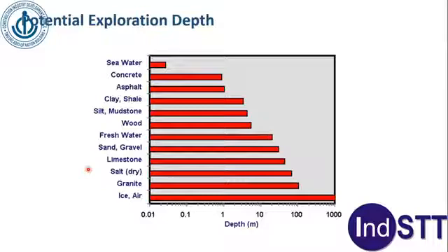It depends on the material. If the material is very conductive, GPR is almost useless. If the material is very resistive, GPR will have great depth of penetration. As you can see, seawater has almost no depth of penetration. As we go from very conductive to very resistive, you get very high depth of penetration.